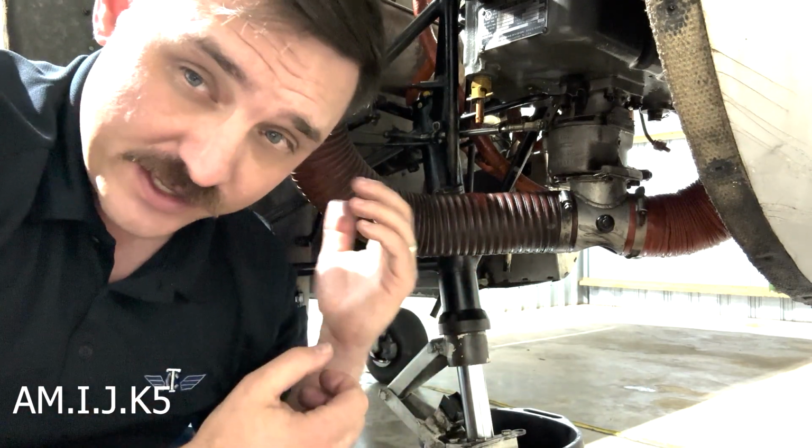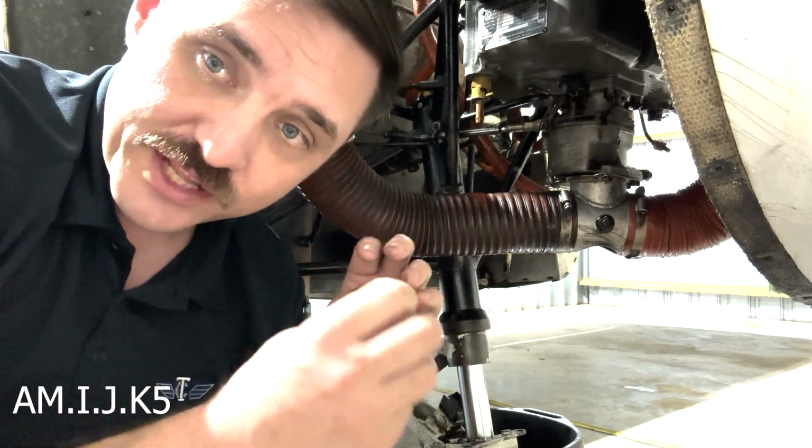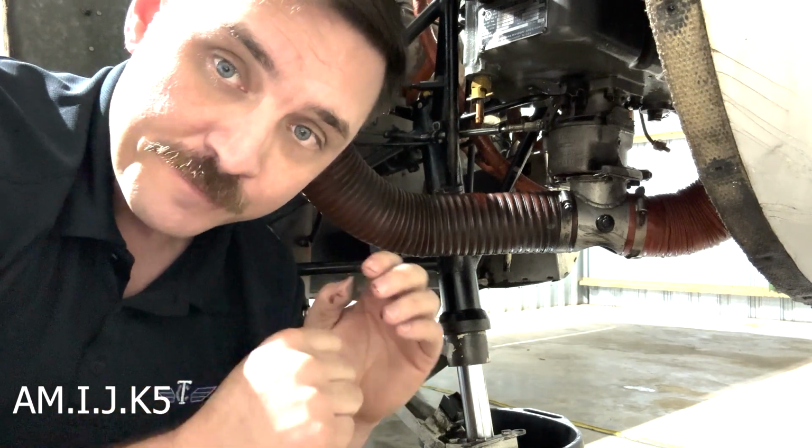Fuel on the other side gets injected into that low pressure area. Now keep in mind that there's an engine driven fuel pump and electric fuel pump on this plane, pressurizing the fuel so that way it goes into that low pressure area with some gusto, and then from there the fuel air mixture gets piped up into the engine's intake manifold.